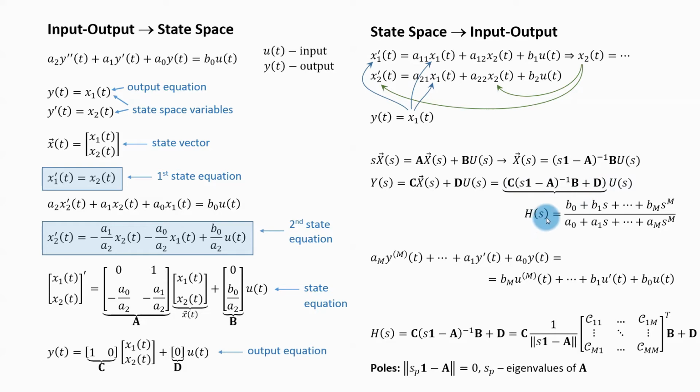Now the transfer function can be written in the form of a rational polynomial function like this one. And these A and B constants correspond to these A and B constants in your differential equation, which is the input-output relationship. So this is how you would get the input-output relationship out of a general single input, single output state space representation. Moreover, for those of you who have heard about linear algebra, there is one more piece of information to be found here.